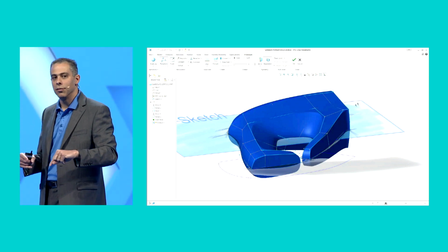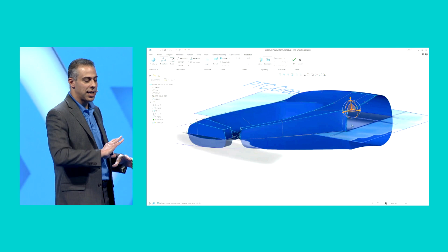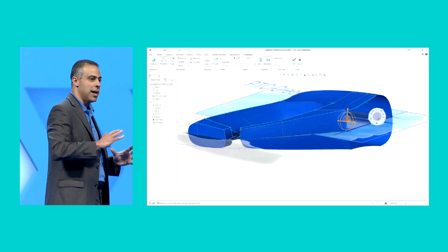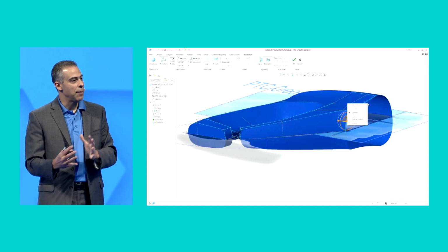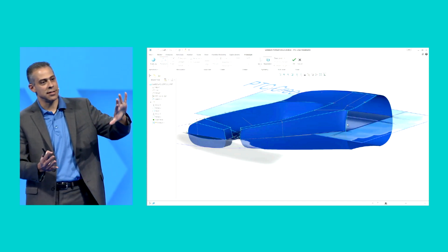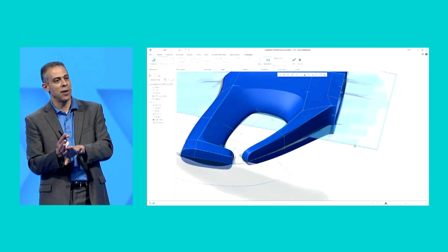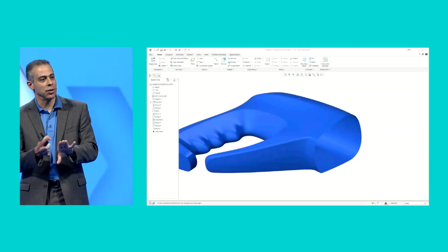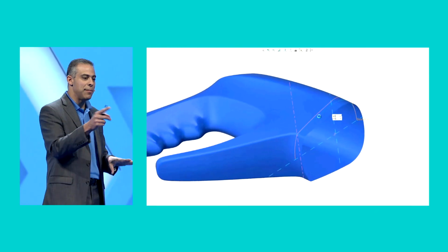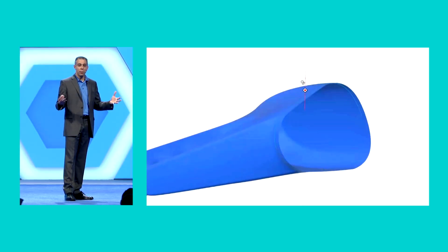But what's about to happen next is the alignment of ISDX-based curves with the Freestyle feature, right? So now you're controlling the boundaries of the Freestyle object. In the front here, I'm taking an initial sketch, and I'm aligning the Freestyle surfaces with the sketch. And I'm not only aligning it, but I'm also telling the system that I want the angle of attack to be normal into those curves. So I can align to surfaces with tangency, I can align to planes or curves being normal. And now when I make a change to that sketch, the Freestyle object just updates and regenerates. Very, very powerful stuff, right?